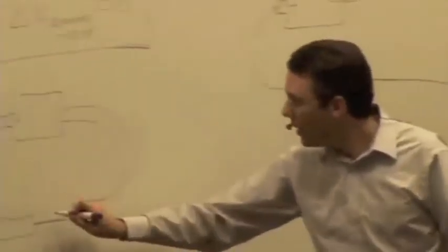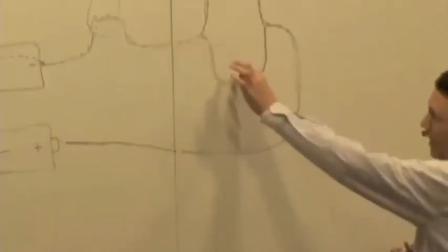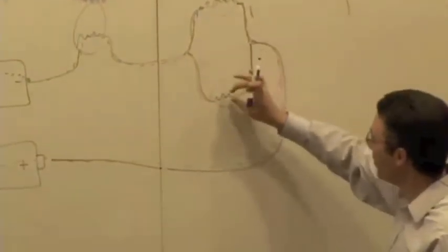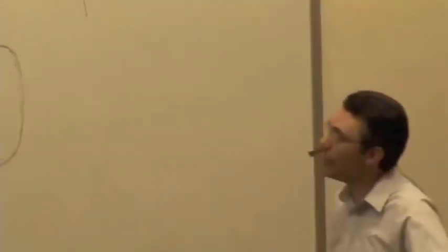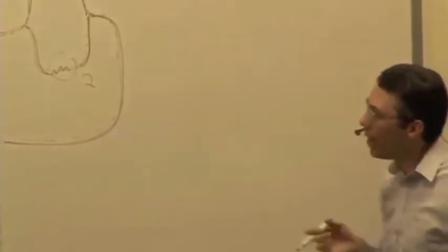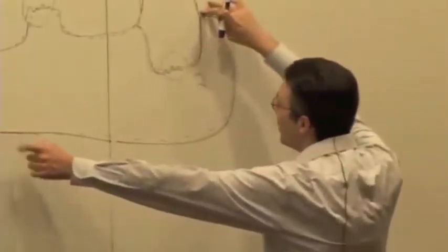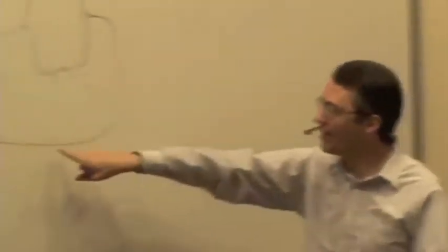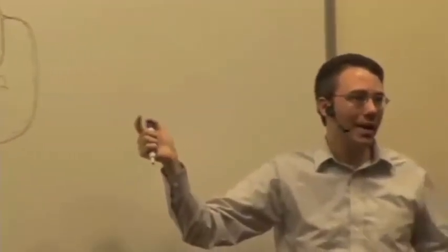It was bigger, right? And in fact, what is often the case in situations like this, the electric field in these thin, what are called resistors, thin resistive elements of the circuit, is so much larger than the field in the thick connecting copper wires, highly conductive wires, that it's very small. It's almost negligible, so the potential differences across these wires are very small. And you actually did an experiment like this. You worked out the potential differences across different parts of a circuit element, and you found that across the connecting wires, the voltages were tiny, like 0.01 volts, in the millivolt range.